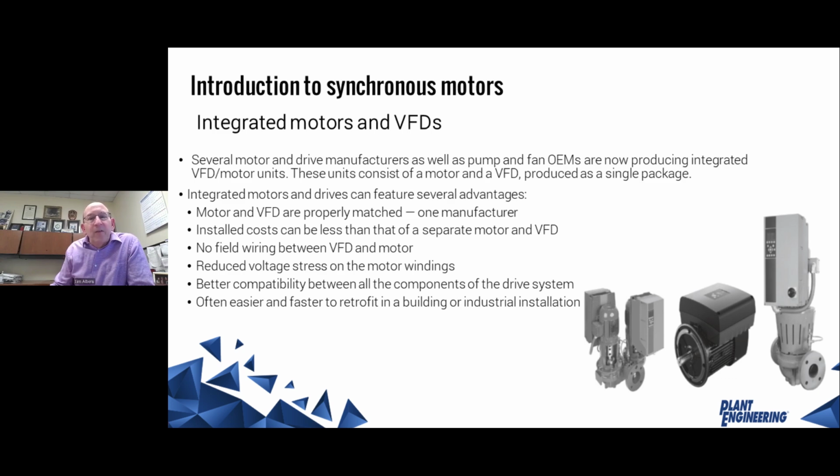The nice thing about an integrated motor and drive is obviously you're getting it from one manufacturer, there's no field wiring, it's good compatibility, and it should be easier to retrofit. So that's definitely something when it comes to integrated. Whether you call it an integrated motor and drive or you call it an ECM, it's definitely something to consider with synchronous motors.